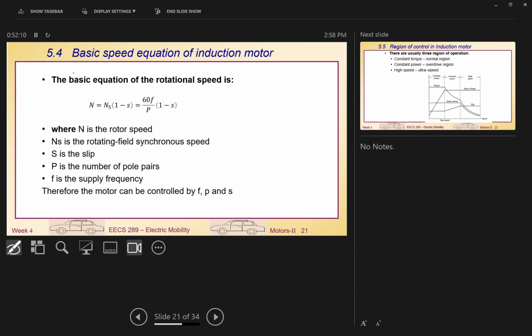When the slip is equal to 0, that means we cannot generate any magnetic force. However, the slip is usually controlled to a small value, usually about 5%. Then you get something like 95% of the power frequency becoming your rotating speed. So that's how you operate. The best operation will be roughly 5 to 10% slip for most induction motors. When the motor stands still, just starting, the slip will be really large, and then we don't have any magnetic torque anyway.